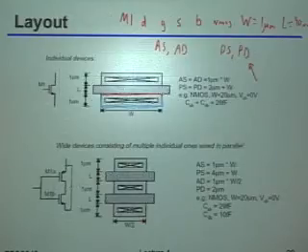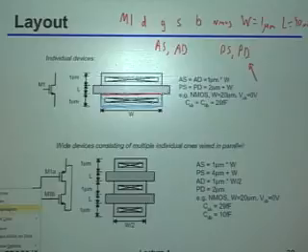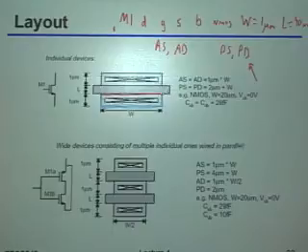Okay, so if we come back to this picture here, the real critical point is that if you don't know how the model is set up, or if somebody hasn't nicely taken it into account for you, you definitely have to add these AS, AD, PS, PD parameters anytime you're trying to instantiate a transistor and get a reasonable estimate of its real performance. Maybe the most practical way to highlight that is that if you do your project and you have these amazing specifications, and I open up your SPICE deck and see that there's nothing there, I'll beat you up. Because clearly it's just wrong, right? So keep that in mind, user beware.